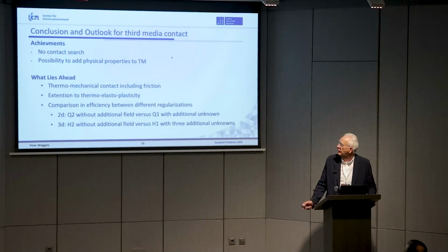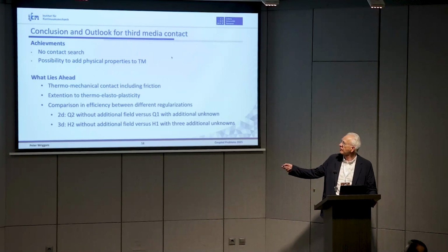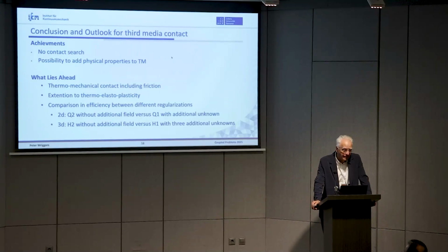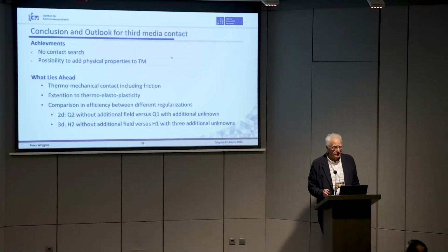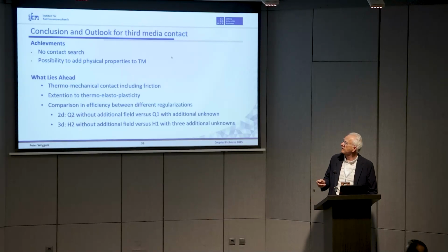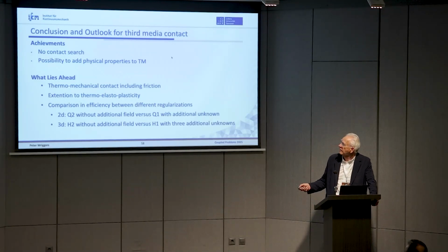So I want to stop here and say, okay, what is the third medium approach doing? No contact search, and it is possible to add physical properties to the third medium, which is not so easy in classical contact mechanics. What I still have to do is include friction. There is some work which already did it, but there is still an open part. It can be done. You have seen that the shearing is possible, so the classical way would be to introduce something like polycrystal plasticity for polycrystals.